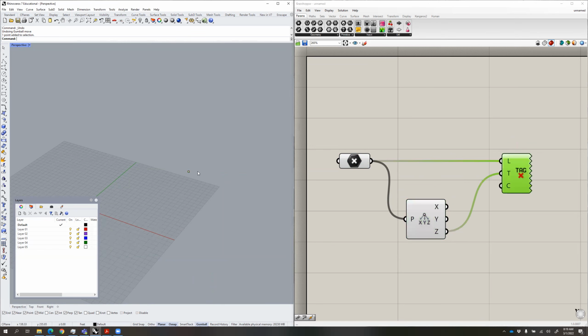And then basically it's really hard to see. So what you need to do is just right click on this here and make the text size large. And so now if I move this point in the vertical Z direction, you'll see that now it's beginning to visualize the actual elevation of that point. And this, in landscape architecture, is, in my opinion, the foundation for all good modeling. You just need good spot elevations. You need to have the ability to easily draw geometry.